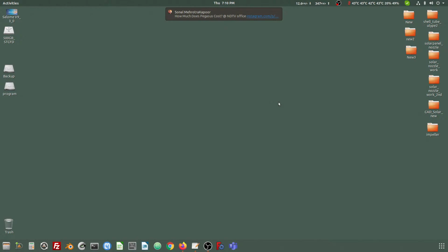I have considered one problem which I am going to demonstrate with two different solvers in OpenFOAM: simpleFoam and pimpleFoam. Basically these are two solvers. pimpleFoam is used for unsteady-state incompressible flow analysis, and the simpleFoam solver in OpenFOAM is used for steady-state incompressible flow analysis.